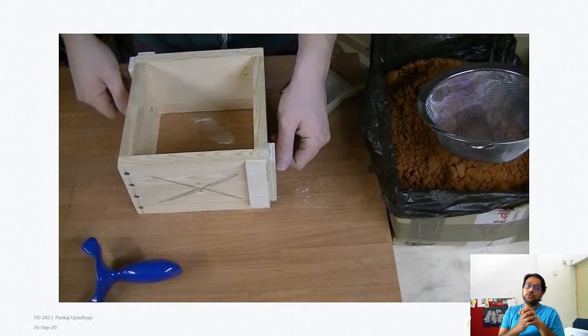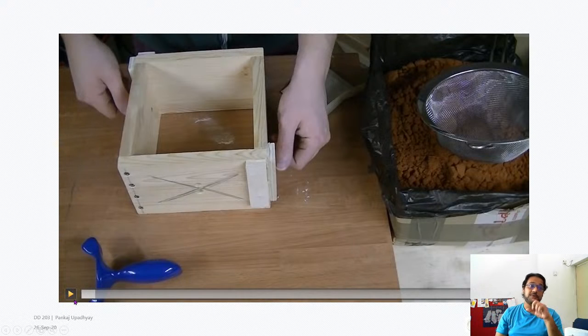There's a very nice thumb rule to check if the sand is good for casting. You take the sand in your hand, clench your fist and open your fist. The piece of sand should retain its shape, and if you tap it slightly, it should break. That is the consistency you want: not too wet, not too dry. If the sand is too wet, when you pour metal, the water in the sand will evaporate and the water vapor will bubble into the molten metal, and you will get small bubbles internally. That is one of the casting defects. We will talk about this later.